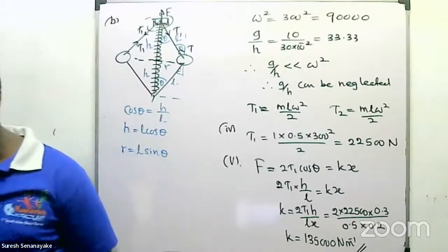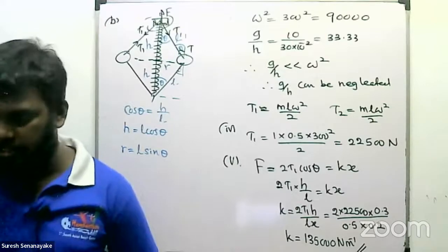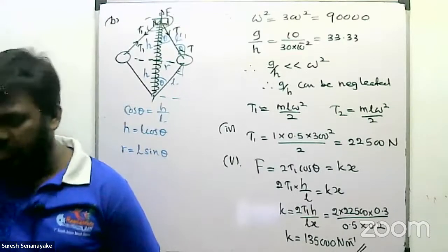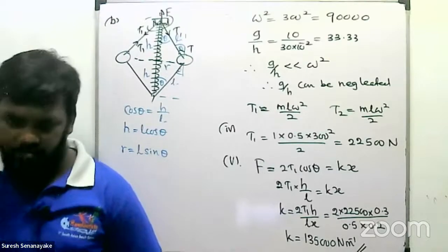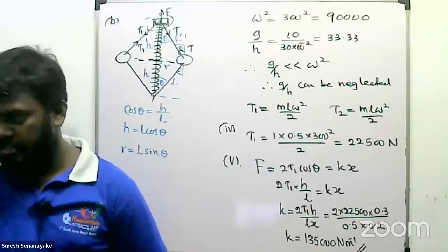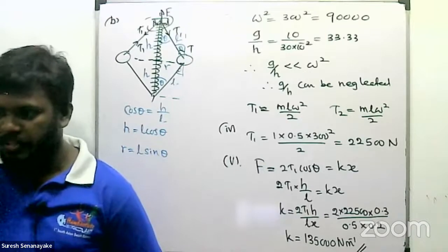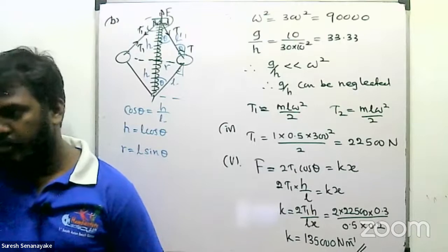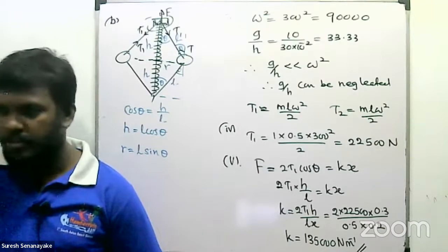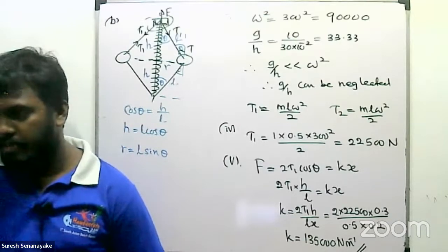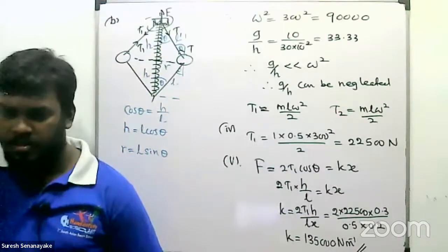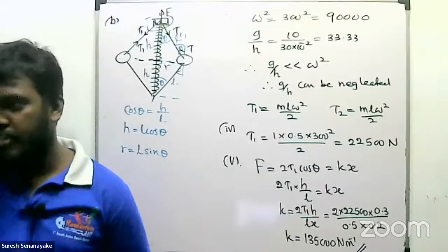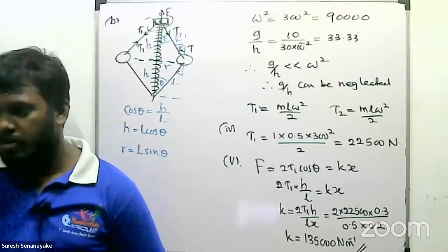Frequency of the output voltage depends on the consumption of electricity. When the consumption increases, the output frequency decreases, and vice versa. According to the design, when the frequency of the output voltage becomes 25 hertz, the throttle valve will be fully open. It's fully open, right? Fully open means that is 0% block.